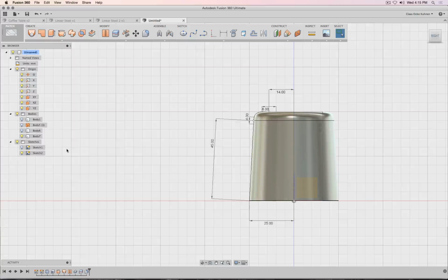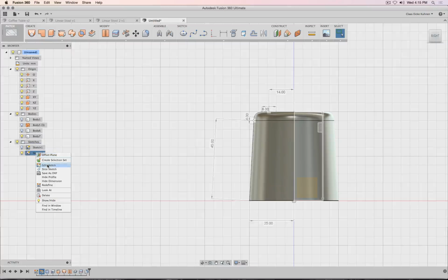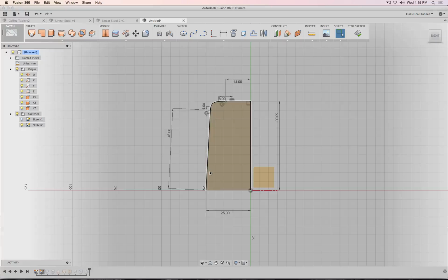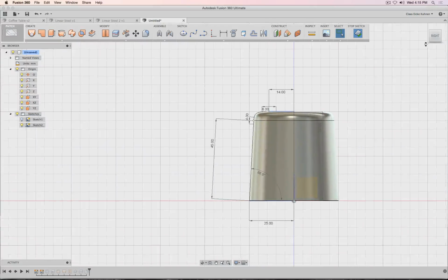Also, by the way, I didn't show that yet. Actually, if you would like to have control over the radius, you can actually select these two lines, then go to sketch dimension, and then the software understands, oh, you mean the radius there. Because if you select 2 points, it understands the length, or between this line and this line, the distance. So it's actually a pretty smart dimensioning tool. So that's it.